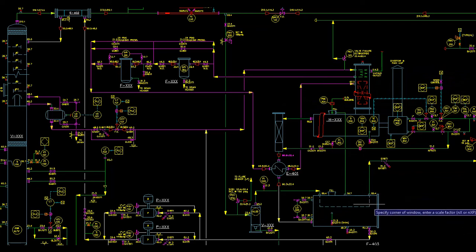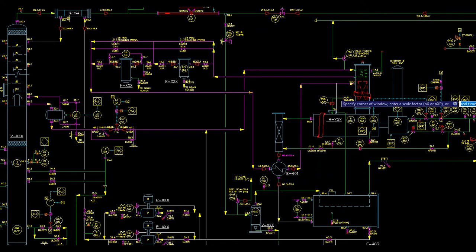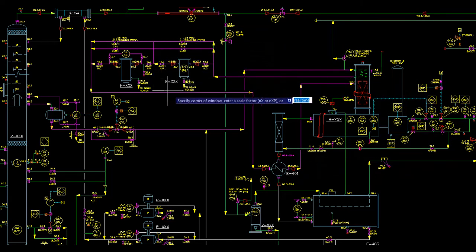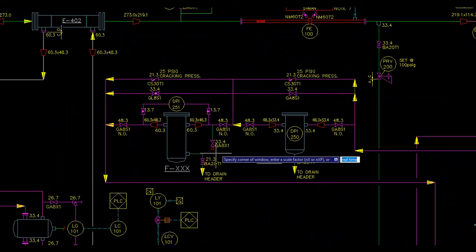Following the rich glycol path from the coil, it will go to the filters. The sock filter will take out any solid particles. The carbon filter will absorb hydrocarbons, if any.